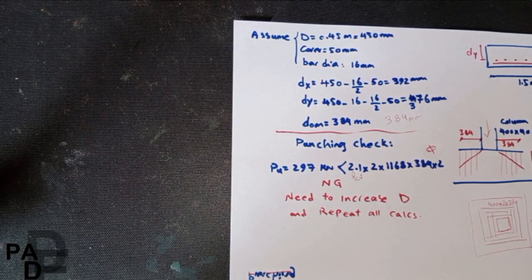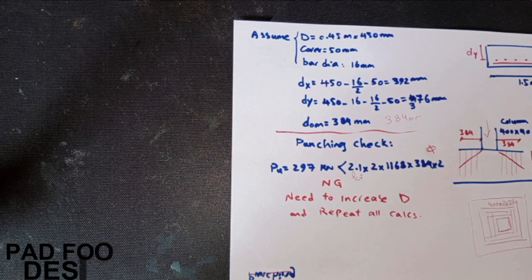Okay, these are the basic rules for any foundation design. We worked on single pad footing design for simplicity, but the rules are the same for all types of footings. Doesn't matter if it is centric or eccentric loading, or we have one type of loading, or what's the type. It is just point load or distributed load on the pad, or even we have bending on top of that. The rules are the same. We need to check for soil capacity, pad capacity, and also punching capacity.